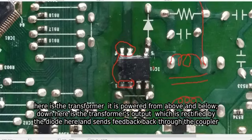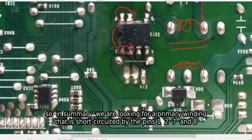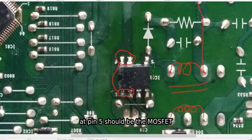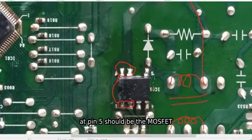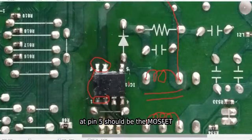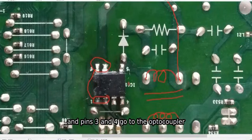Here is the transformer. It is powered from above and below. Down here is the transformer's output, which is rectified by the diode here and sends feedback back through the coupler. So in summary, we are looking for a primary winding that is short-circuited by the pins 1, 2, 7, and 8. At pin 5 should be the MOSFET. And pins 3 and 4 go to the optocoupler.